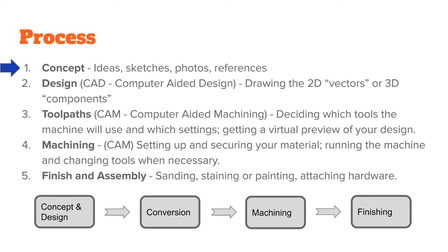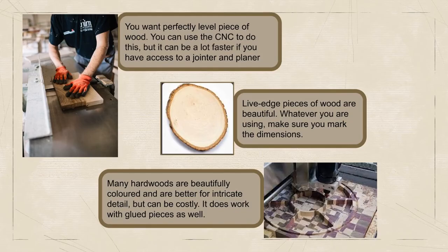It begins with a concept or an idea of what the desired product will be. At this stage, you will also want to select your material to be carved. At least one flat side is needed so that the workpiece will remain steady during the milling process. Please remember that the end product can be damaged or ruined should the workpiece move while the CNC is carving.